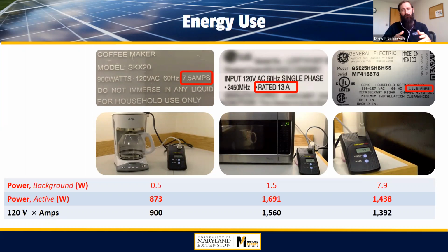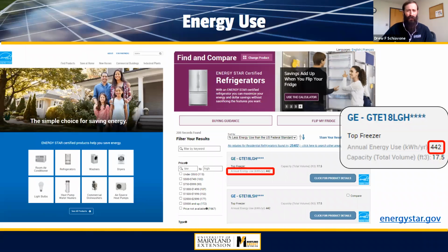And when we actually start to talk about how we design the PV system around that, we typically look over an annual period and we capture some of the seasonal variation as well, more so than just a local demand, because we might miss some of the features that we see with different equipment. So, you know, that's kind of a small scale how you can look at individual devices.